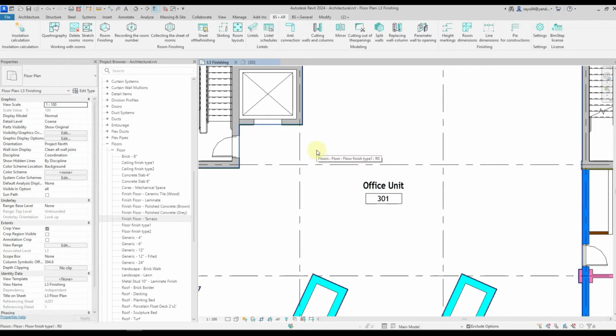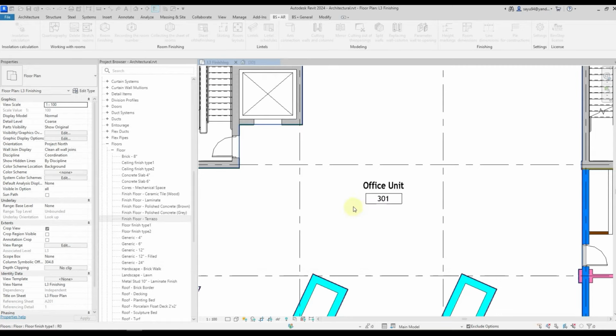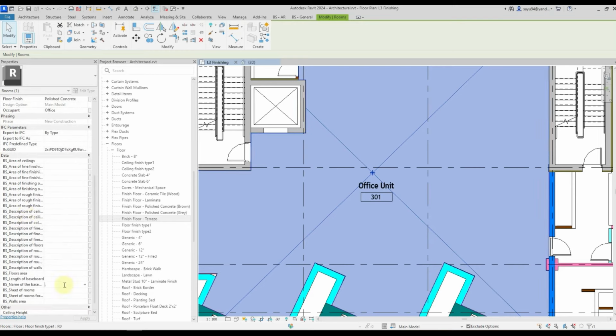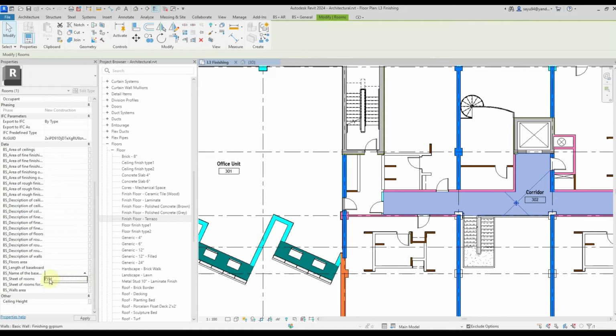We recorded the rooms, and now we can go to skirting board calculation. If in your settings you didn't tick the box for a skirting calculation, then you can skip it. But if you want to consider skirting, then it's absolutely necessary to do it. In order to count the skirting, select our room and the parameter called skirting name. For each of the rooms, we must write the type of skirting board. Let it be PVC skirting board, both for one room and for the other. That's all we need to do for a skirting board calculation.